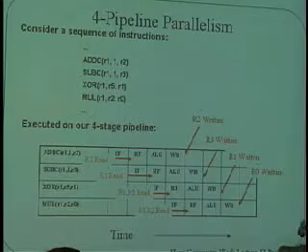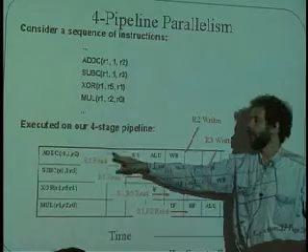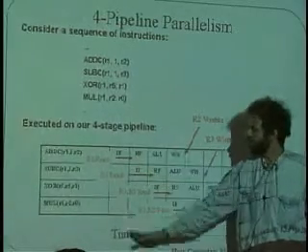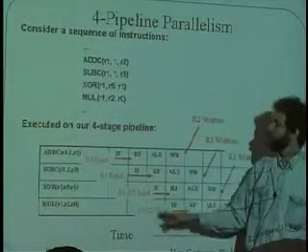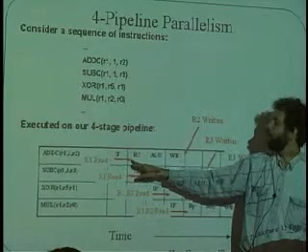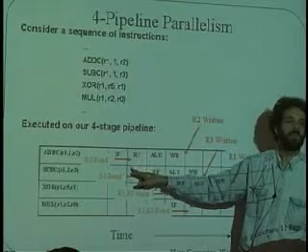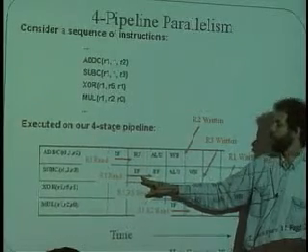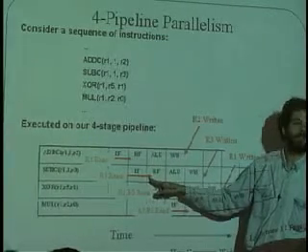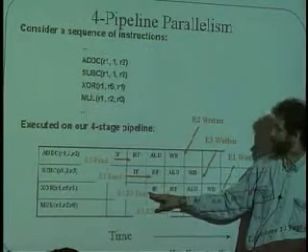Well, what's neat about this is that you'll notice that this instruction starts off and it fetches the add C. Next, it goes down the pipe by one stage, and each one of these lines here is a clock edge. And it starts to read the register file. And so it reads R1 right here. While it's reading R1, this instruction is being fetched from the memory, the big slow memory. And then when it's doing its ALU, this one is reading its version of R1 from the register file. And while that's going on, this third instruction is being fetched.